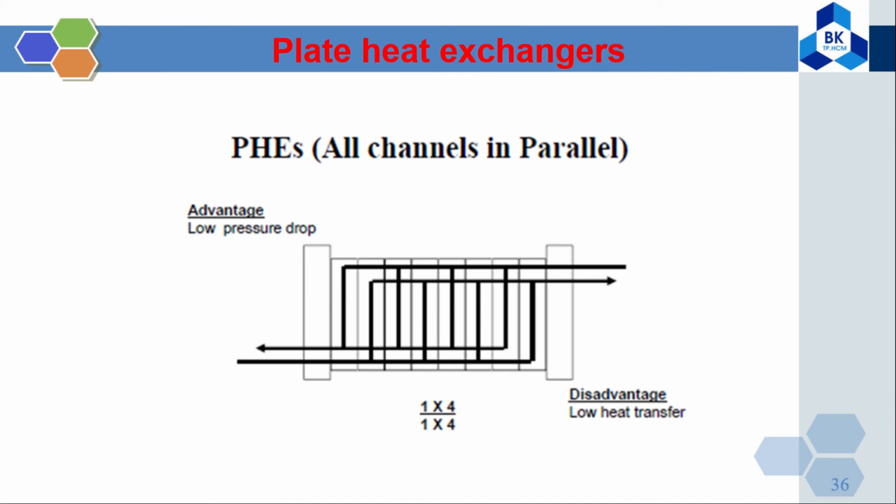And for the plate heat exchanger, they can put all the channels in parallel. Look at the picture here. You can see they put them in parallel. So the advantage of the parallel one is to have a low pressure drop, but the disadvantage is low heat transfer.